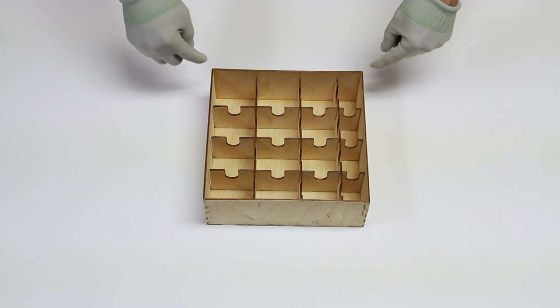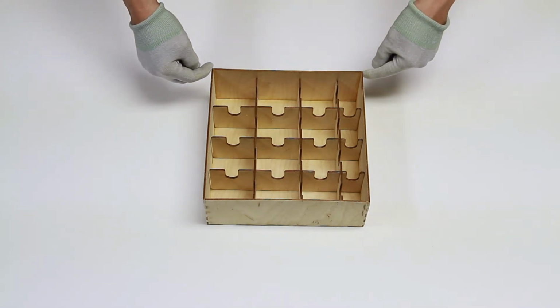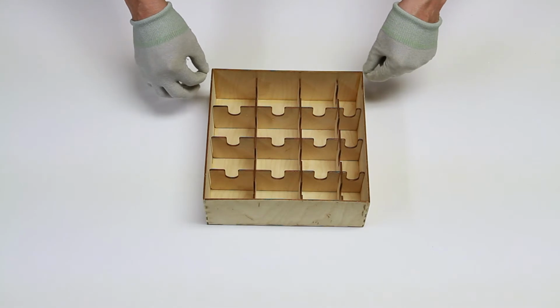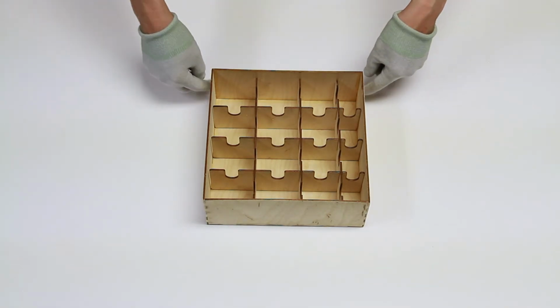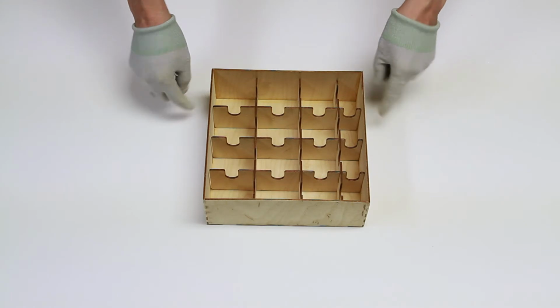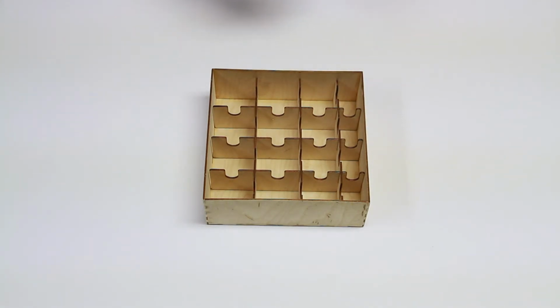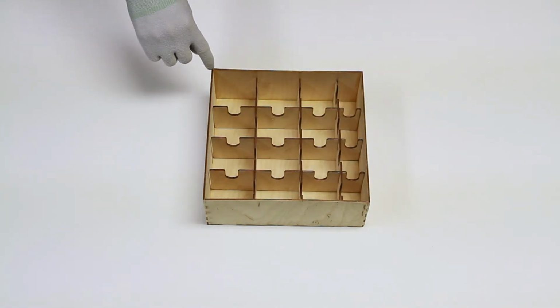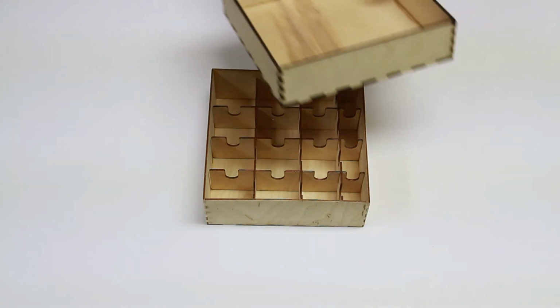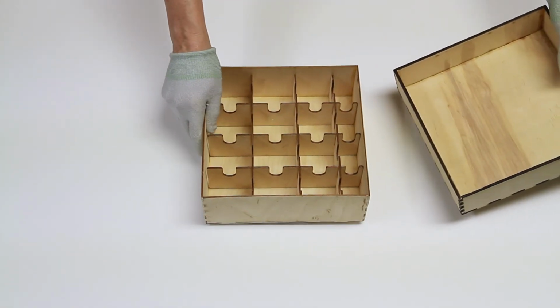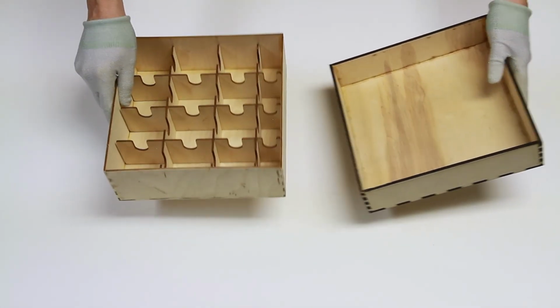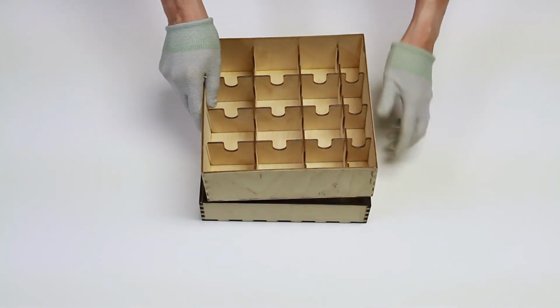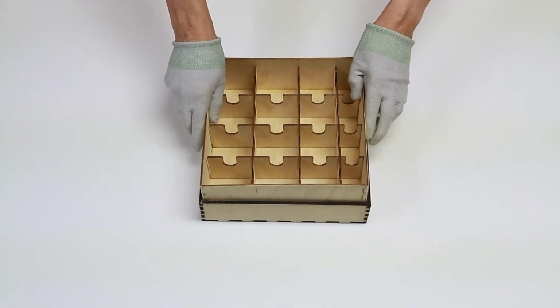We also went ahead and sanded all the edges, because if you're going to get stuck on something, it's going to be burrs or little pieces of glue along the edges. The liner actually goes into the next section. Now, taking the outside dimensions of the liner, adding maybe 1 millimeter to it, or 40 thousandths of an inch, we designed another box with a thicker material, and that box has the inside dimensions based on the liner outside plus that millimeter. So the liner goes into it.